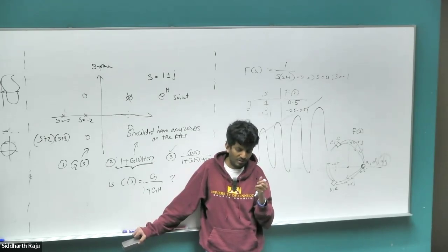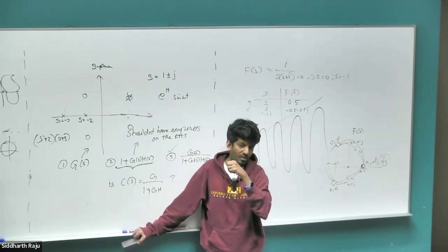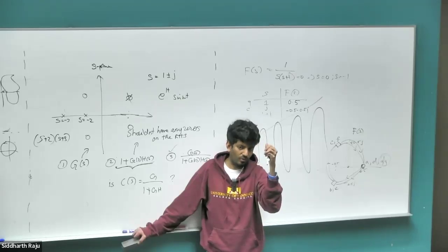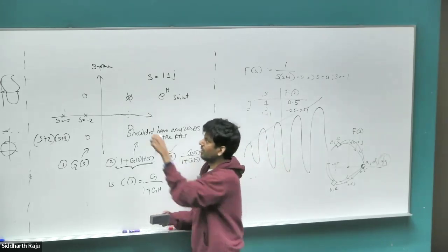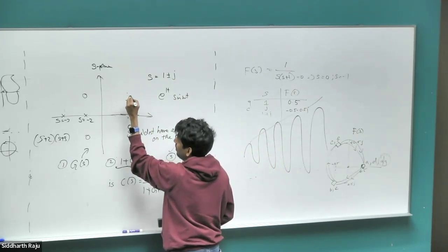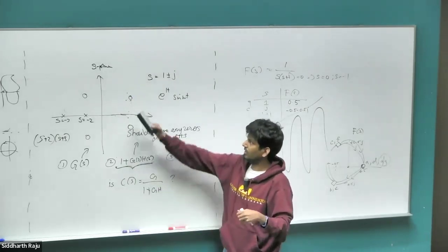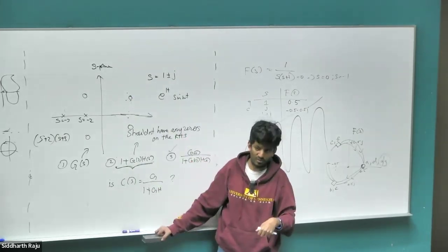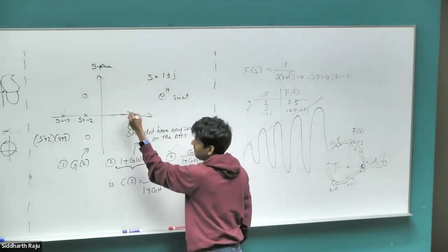Let's say you have an inverted pendulum and it had this characteristic where the open loop system had some kind of pole on the right hand side. And if you try to cancel it out with a 0, you better match it exactly. But that would not be practical in a real world system. Even the tiny difference would still make it unstable. So if I had a 0 here and the pole was just slightly off, a little bit, doesn't even matter, 0.0001 e power minus 20 or 30, that would still make it completely unstable, right? Only in math can we cancel those out nicely. In reality, that wouldn't be feasible.